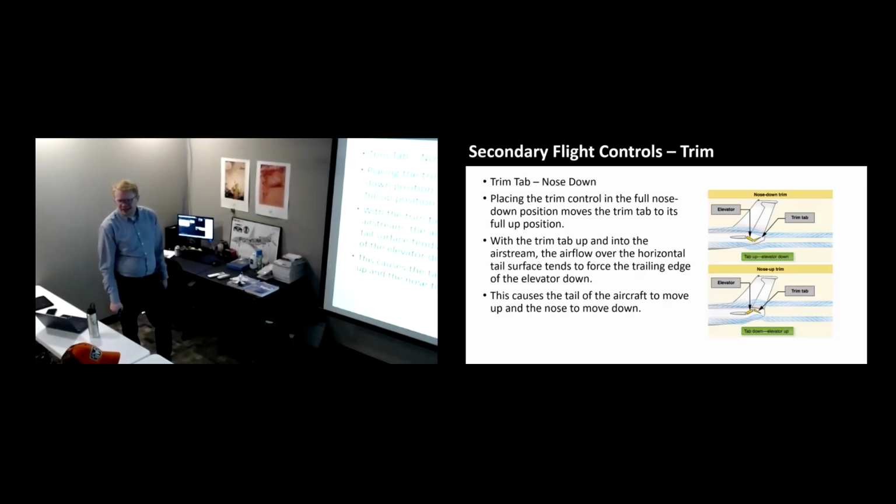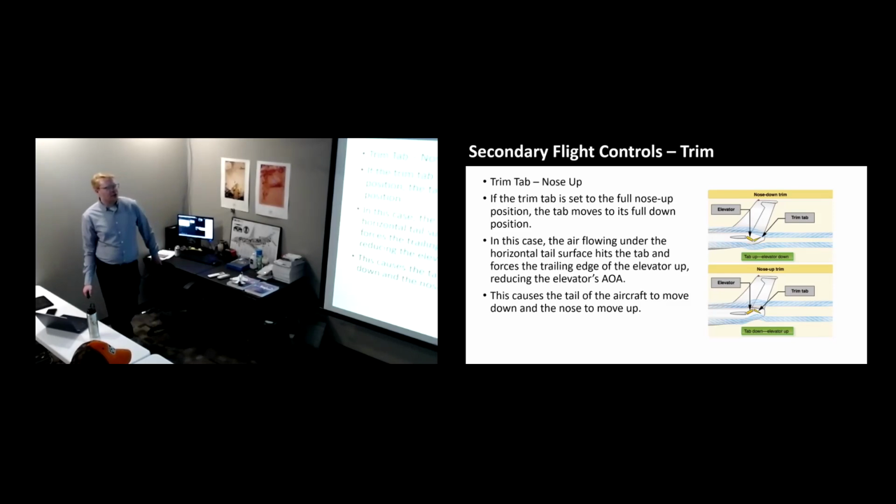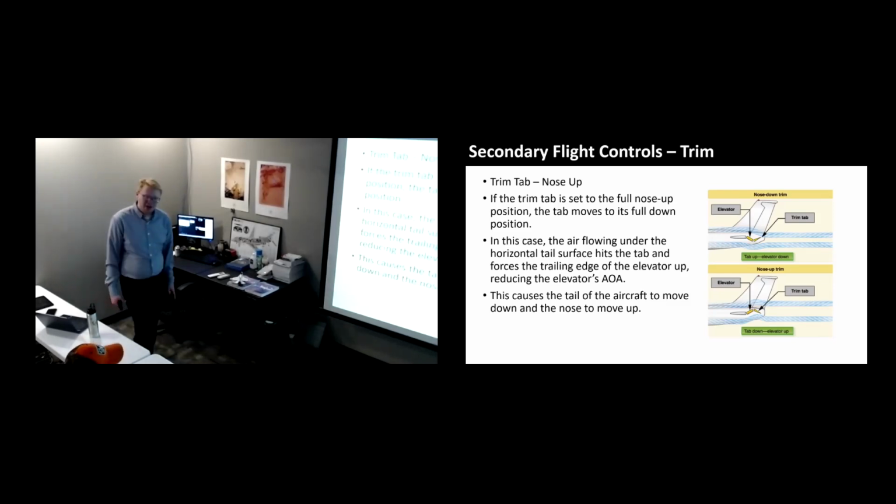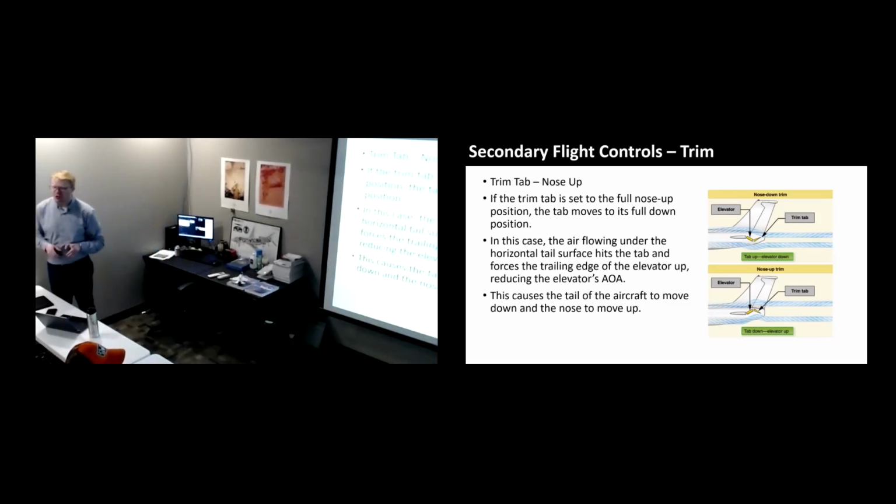Does that make sense? So the trim is on the elevator itself. Yes, the trim tab is physically on the elevator of this particular design, which you'll see in most. It's like trimming a boat. The boat will stay like this until you trim it out and you're forcing the nose down. Nothing too groundbreaking here. And in the reverse direction, nose up, it does that. It's all working on deflecting those forces, adjusting the angle of attack over that piece of elevator and causing the lift change.